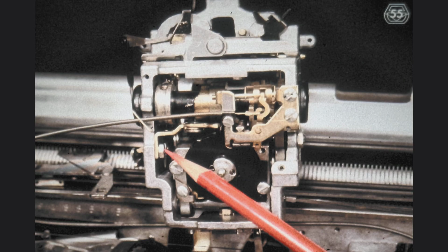This is a bottom view of the carrier. In order to adjust the vertical position of the detent cam follower, we have to loosen the indicated nuts, and there are 2 of them. When we make this vertical cam follower position adjustment, we must also consider that the cam follower should track on as much of the working surface of the cam as possible, in such a way that it barely fails to make physical contact with the print sleeve. Do not let the cam follower rub on the sleeve.